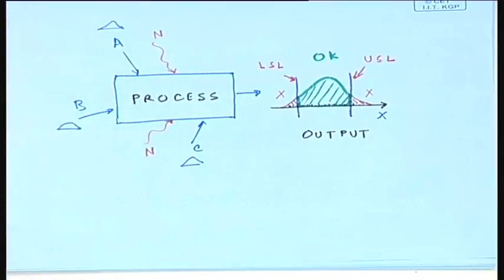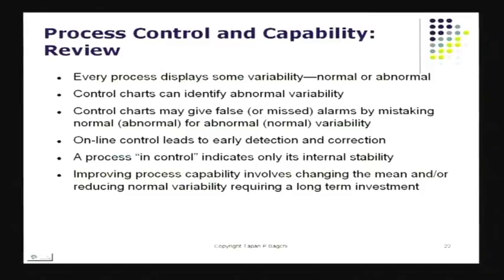Suppose the process was not disturbed. It was just statistical variation that led to that condition there. You end up needlessly troubleshooting the process. That can happen because with the control chart, there's a teeny chance, 3 or 4 parts per thousand, 3 or 4 data points per thousand, when the chart itself may give you a false signal. That is there. And this is the type 1 error.